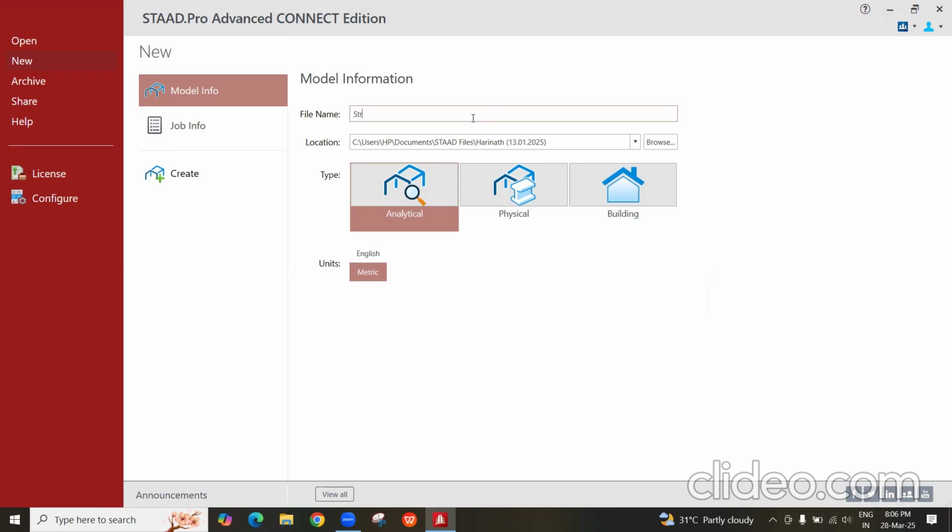And you said you want to know about time history analysis and all. This is spectrum analysis, this is time history. Response spectrum analysis is also there, so these are correlated. Response spectrum analysis is required during blast conditions, so we will see that later. Now we are just finding the basic frequencies using two methods, Rayleigh and the eigen extraction method.